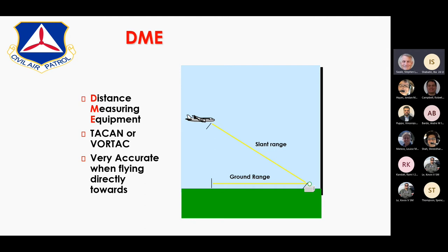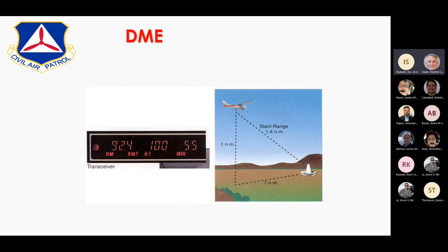And also notice that when you get to 5 or 10 miles away from a DME transmitter, the slant range is really negligible anyway. At 1 mile away, you've got a 0.4 mile error. Once you get to 10 miles away, it's significantly less, since we're operating more like 1,000 feet, not even 5,000 feet high. And then here's another picture of that. This is a picture of the old 6-pack style of DME. And again, there isn't even a box like this in the G1000 aircraft. It's synthesized from the GPS position.